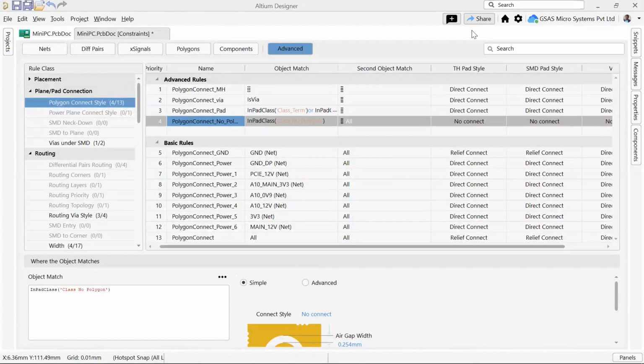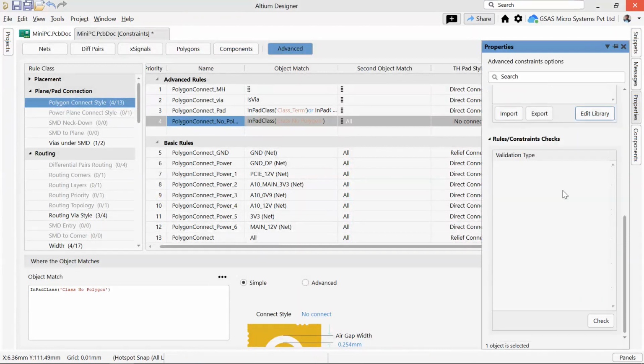You can easily catch them by using this option available in the latest advanced editor, the rules and violation constraint check. If you click on check, it will see whether any errors are found, any duplicate errors, any violations in the rules. It will try to figure it out.